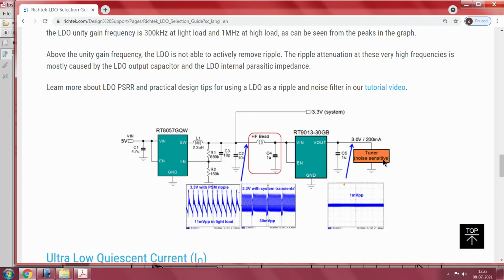This paradigm you should never ever forget, folks, never ever forget. I must tell you that you must sleep with this picture in your mind, that with LDOs you typically must have a difference between input and output which is not more than 0.3 or 0.2 volts.